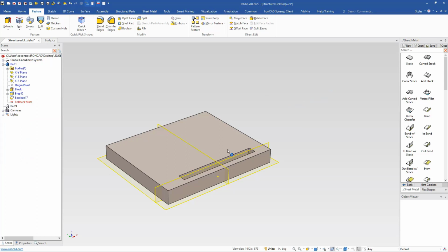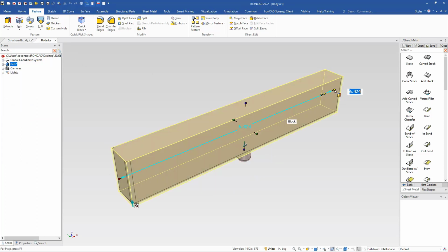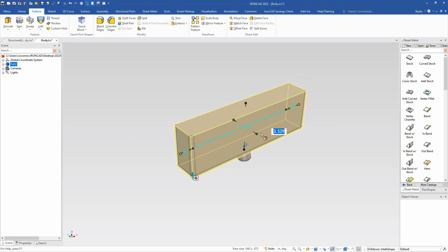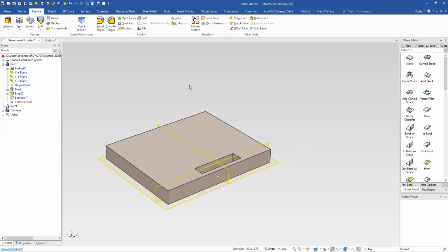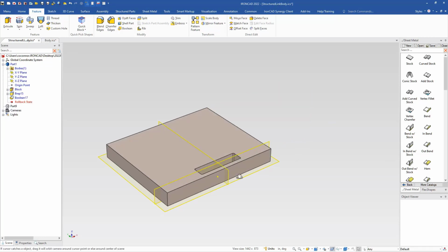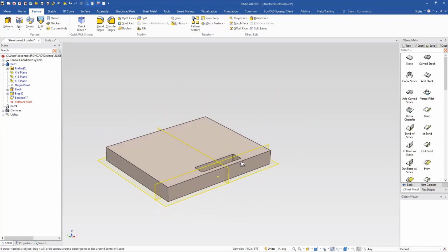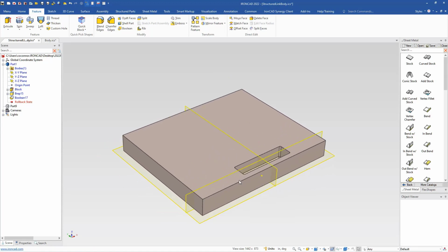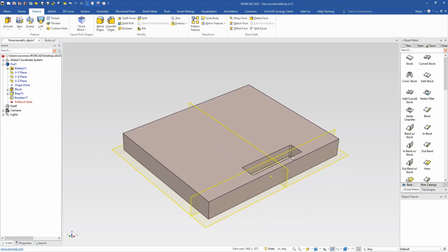And we can see that our file still maintains our geometry, but even if we go to our external file and make changes, for example, maybe we'll make this a little bit smaller, maybe a little bit wider inside of here. We go back to our structure part, you can see that that automatically updates and maintains those changes. So a very handy feature, not only just to copy bodies from part to part, you can actually use the linked body for internal parts and external parts to use this as operations for such things as adding geometry to your structured part or removing geometry for things like molds in your designs.